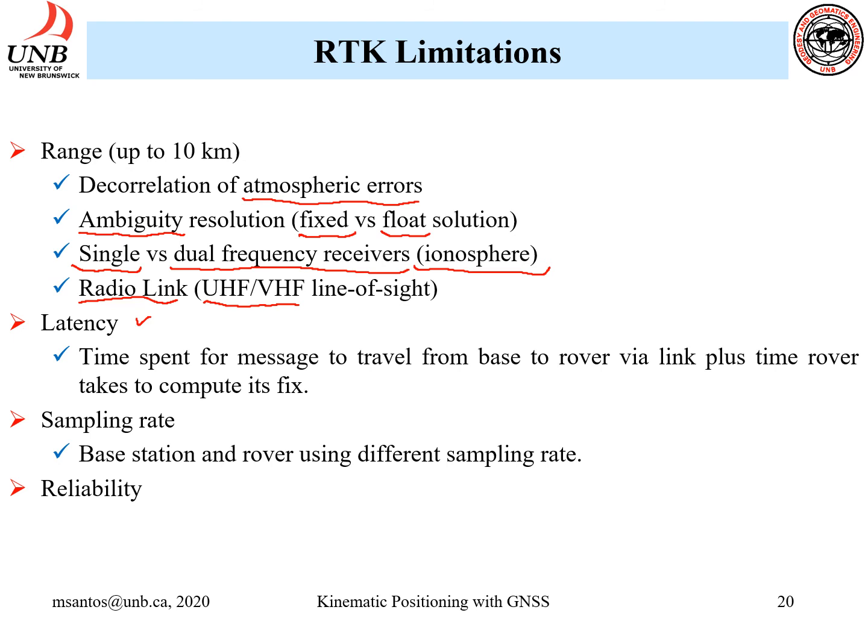So a good definition of latency is the time spent for the message or the observation to travel from the base to the rover via the link, plus the time the rover takes to compute its fix, its position. Sampling rate and reliability.